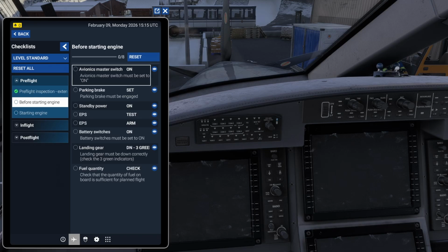And the next checklist is, I would say, before starting the engine. What you will see in the real checklist from the real aircraft is that it normally divides it into multiple sections. Normally it's the empennage pre-flight check. Then we've got the right wing trailing, the right wing leading. You get the nose section, then the other nose section, then the left wing leading edge, and then the left wing trailing edge. And then you are in the cabin, right, where you need to make sure that the cabin is loaded, the hand luggage is stowed, passenger doors closed, etc.